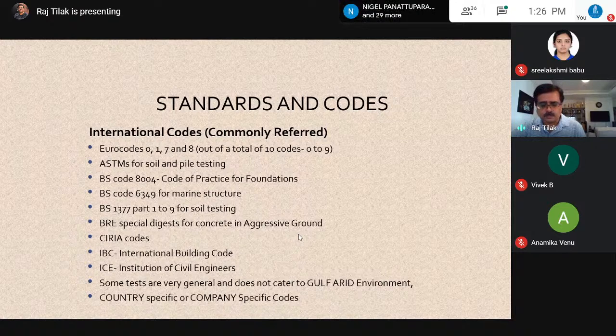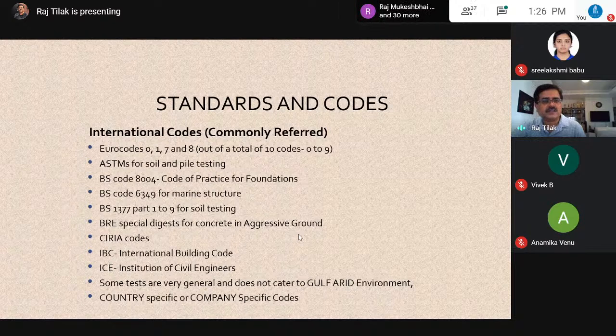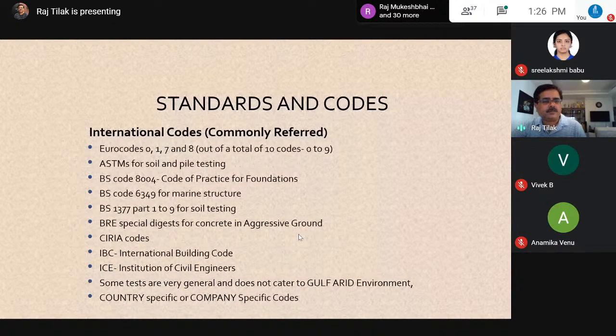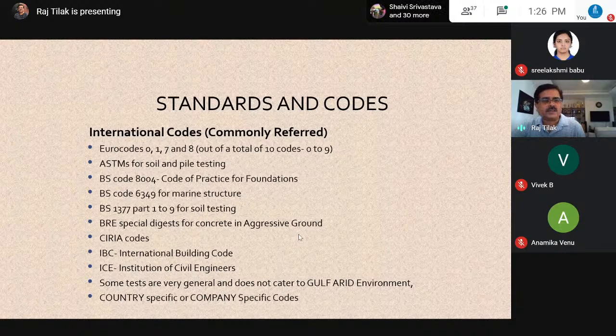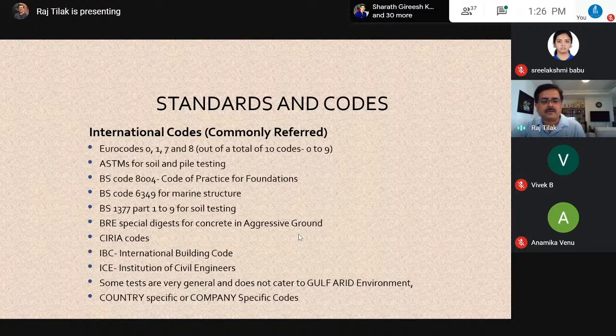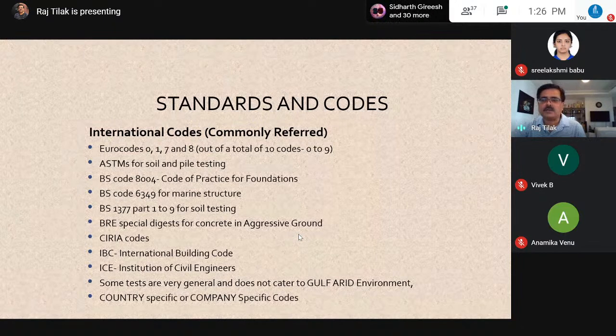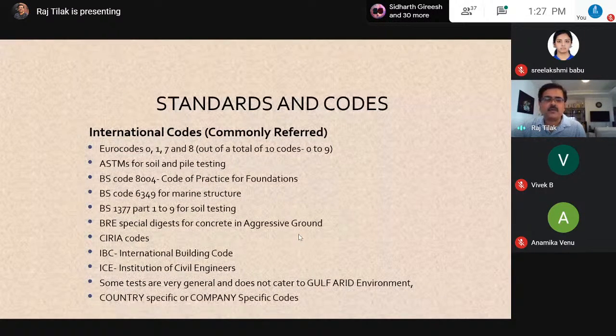Similarly, even in Eurocodes, you probably know that there are lots of national annexes attached to the main body, and each annex is offered by a different country differently because they follow certain things in a different way. But saying this does not mean that whatever structures were designed based on original BS codes are no more relevant. Eurocode has introduced partial safety factors, which is a kind of optimization, wanting people to work in a particular way, but it does not rule out that whatever we had done in the past is of no significance.